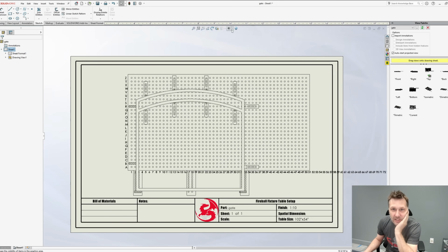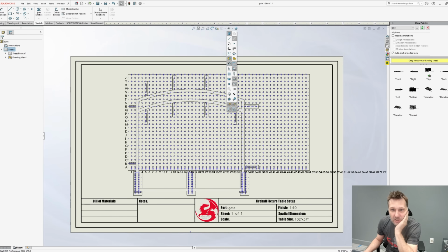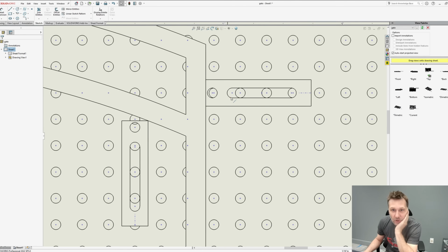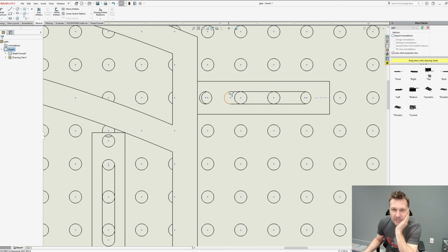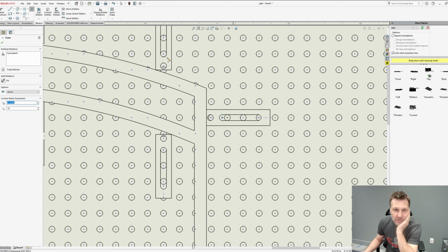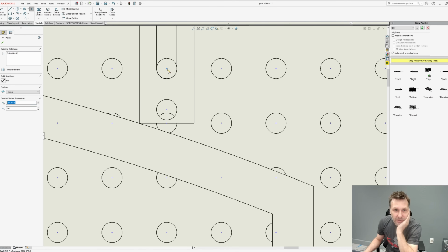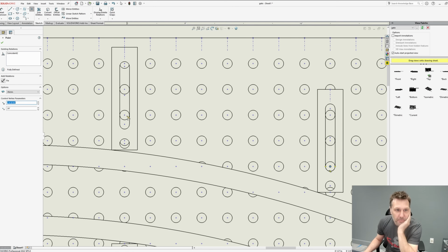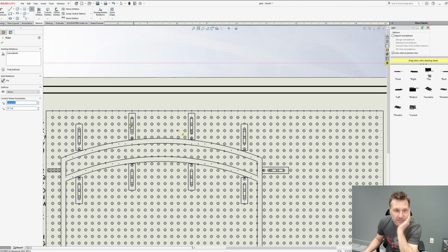So what I want to do is in here we can find the center of the holes by toggling this little icon right here. And this gives us the center of every single hole. So this gives us the center of this end of the slot, which is technically the hole. And this is what we're looking for. This distance right here to here. How far off did this tooth block extend off of that hole? So I know from experience that SolidWorks has a pain in the butt selecting those marks. So I'm just going to come through here. That one looks like it's pretty much right on the money. And just give myself these targets to pull measurements from.